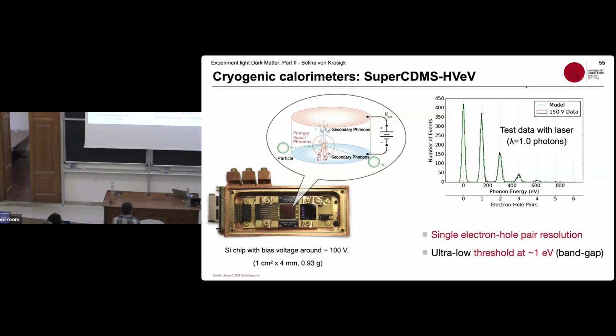However, it could still be that, and we call this impact ionization, the electrons that you're accelerating are not just generating phonons, but on their way they could kick out another electron that's still sitting in a shallow state. And then along your way, say halfway through, you're getting another electron contributing. The resolution here was not yet, or this is not in log scale. When you go to log scale, you would actually see in-between fill-ins that come from this impact ionization, because you get a partial amplification. Later on I think I have a plot that shows it. So these things happen and they need to be taken into account.